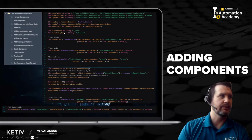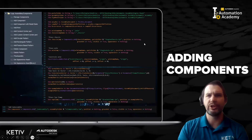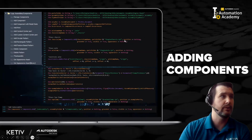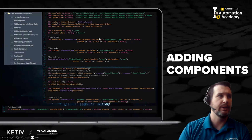We're going to get several different documents, and we'll look at this in Inventor in a second. Then we'll actually use the snippets. When we jump in, you'll see that we can add these snippets here. They'll have some generic values in them that will change around. You can see that we're putting in the component name that will go in once we call it. We're giving it a path, which is this parts folder plus the part name that we want to go in.